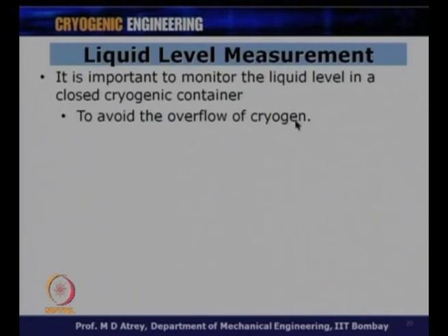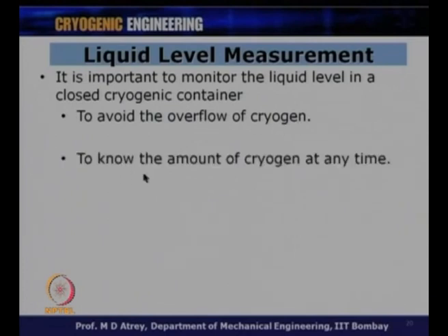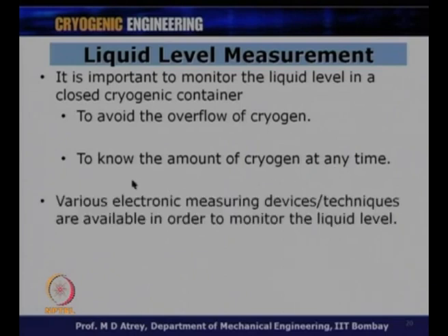It monitors how many liters of liquid helium or nitrogen is left, and correspondingly you can plan your experiments. Liquid level monitoring is important to avoid overflow of cryogen, that is A. And B, to know the amount of cryogen left at any time.